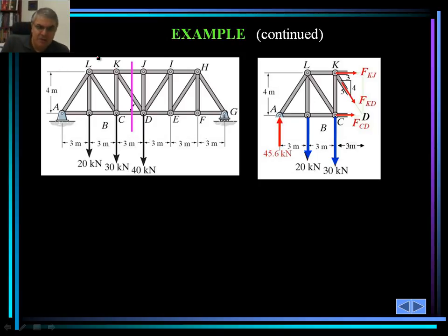Remember, for such a truss, we are going to have two reactions. One is in this way, one is in this way, and for G there will be one reaction perpendicular to this surface that I just marked by red. So there will be three of them, and there will be three unknowns. We take the summation of forces in the y, set that to 0. The summation of forces in the y direction, which is upward to the page, we call this y, and we call this x.